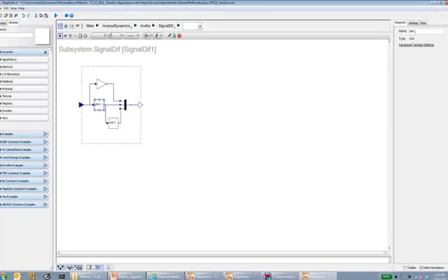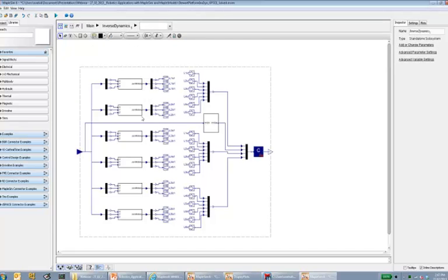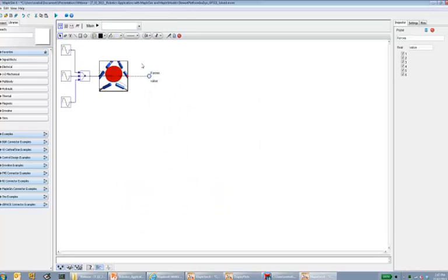So we have symbolic differentiation blocks, 2 of them, for the first and second derivative, and these blocks are used to calculate the signal's first and second derivative, and then all of that is combined and given to the C block, and the result of that will be the forces for the inverse dynamics of the Stewart platform.